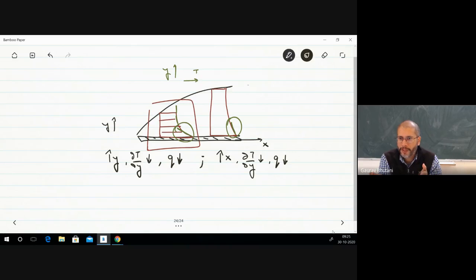Okay, so if for some reason you had to maintain a constant plate temperature, let's say now the plate is losing heat, and because of that the plate may get colder. But if you did not want that, you wanted the plate to maintain a constant temperature, then you would want to have heaters attached in such a way that these heaters provide heat to different parts of the plate differently. Otherwise, if you have a constant heat addition at all the different parts of the plate, then you will not be able to maintain the same temperature, because the heat loss at different points in the plate is different with x. Okay.